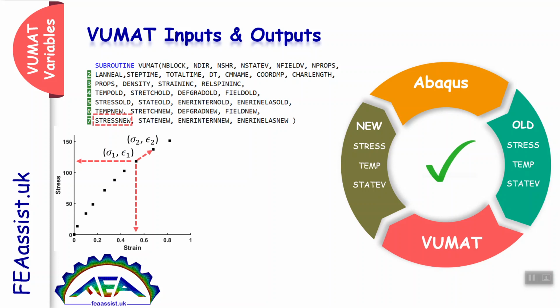In a dynamic way, the strategy is that the new value is the old value plus the derivative function, which is a function of the slope of the diagram and the incremental amount of the strain, as you can see here. For example, in elasticity problems, the slope is the elastic modulus or elasticity stiffness matrix. Understanding all these variables is necessary to write a good VUMAT.